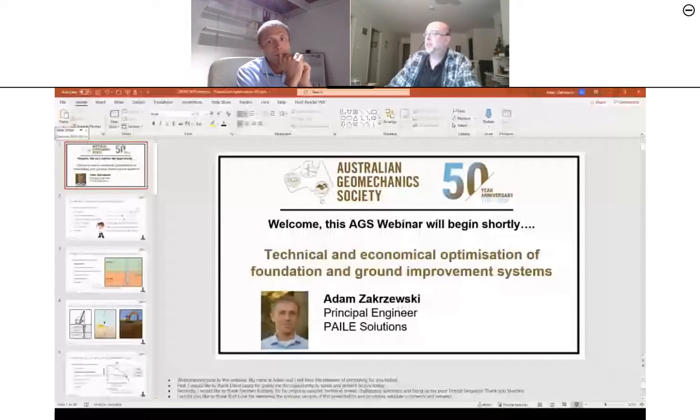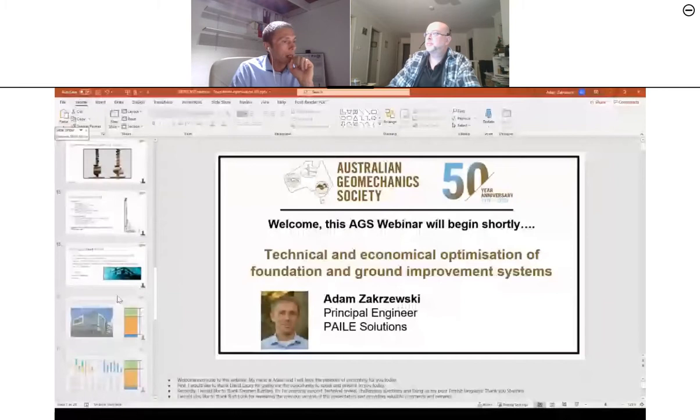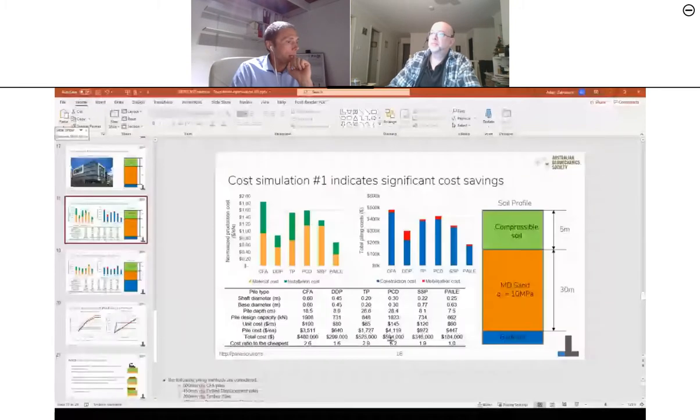Cool, thank you. We have a question. What's the typical maximum axial capacity of the pile? So it will depend on the actual size chosen. In these comparisons, I showed you a pile that has a 250 millimeter shaft diameter with a 750 base, and its capacity was calculated in these particular ground conditions at 662 kilonewtons, and that's a factored capacity.